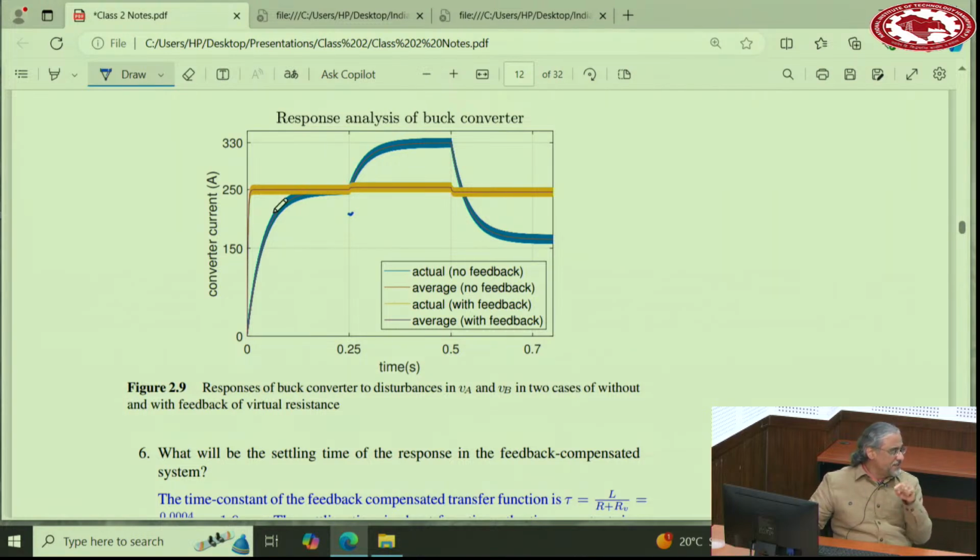And basically, this is the reason that I told you you need to watch out. Because when the response becomes too fast, and some of you may know, in control systems, if you increase the speed of a control system too much, other problems start showing up. And those problems are sensitivity to noise, sensitivity to unmodeled dynamics, sensitivity to nonlinearities, and sensitivity to delays that we have in the control systems. So you don't want to increase the speed too much. And then you see here, there is a little change, not much, and then again a little change here. So this second response is perfectly acceptable.